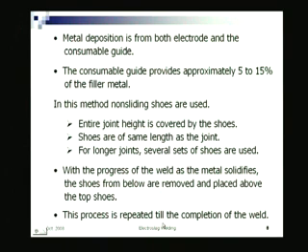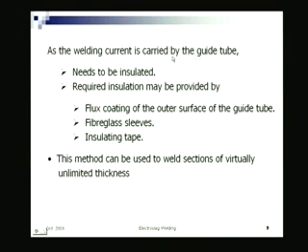The process is repeated till the completion. As the welding current is carried by the guide tube, it needs to be insulated, right. Required insulation may be provided by flux coating on the outer surface, fiberglass sleeve or insulating tape.